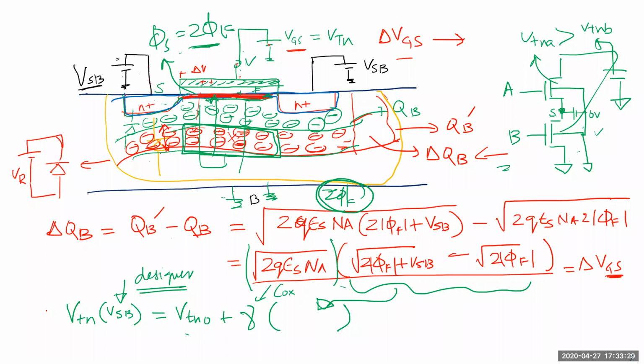But the way you explain it, and the way it looks to me also, the VT voltage which we are talking about right now is with respect to the bulk. Oh, yeah, I probably should make that correction. When I meant bulk, I'm still referring to source, because the source is not changing, because we're talking about change in voltage. So yes, we should always talk about source, because everything is referenced to source.